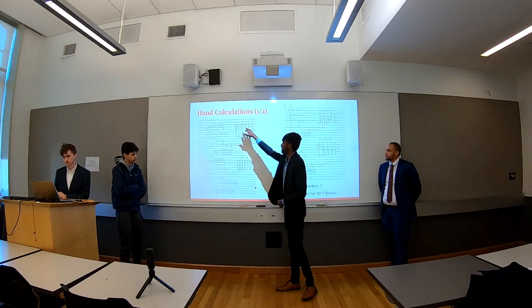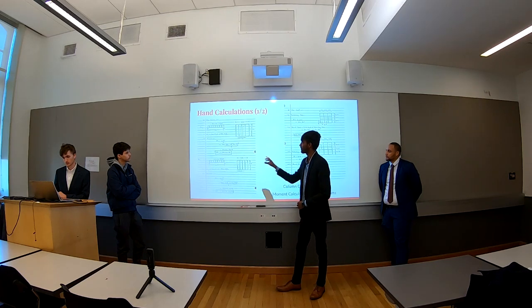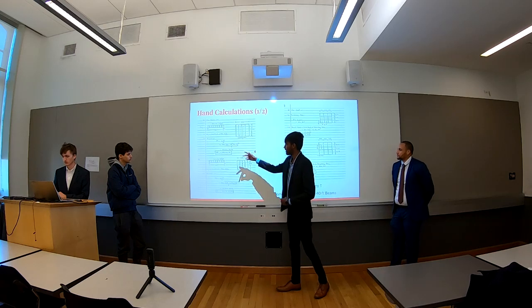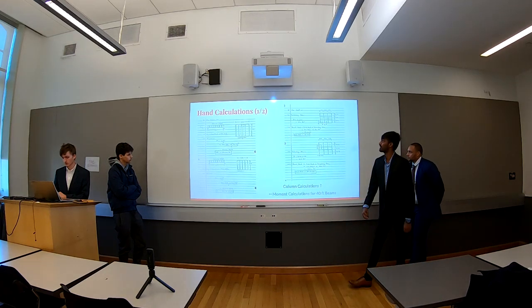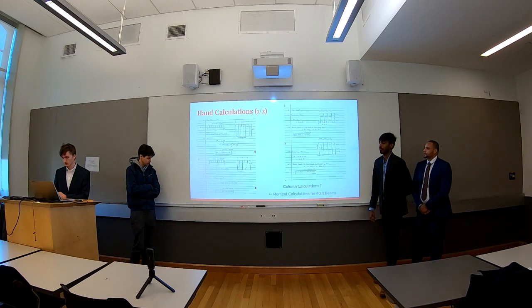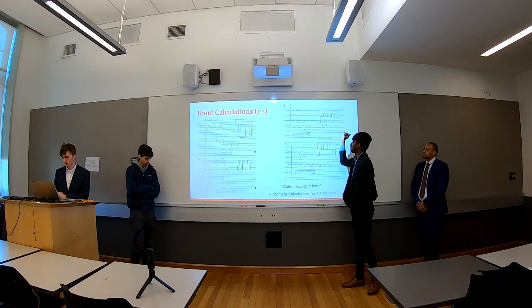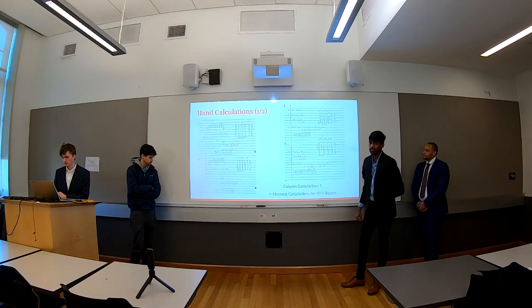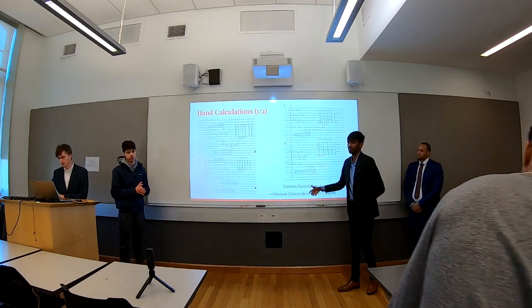That's for the 30-40 floor section, and that's for the 30-30 section. And we got the exact number with ETABS. Similarly, we did calculations for the columns as well by counting the tributary area of the 20-30 section and the 30-40 section, and we got the same result with ETABS.